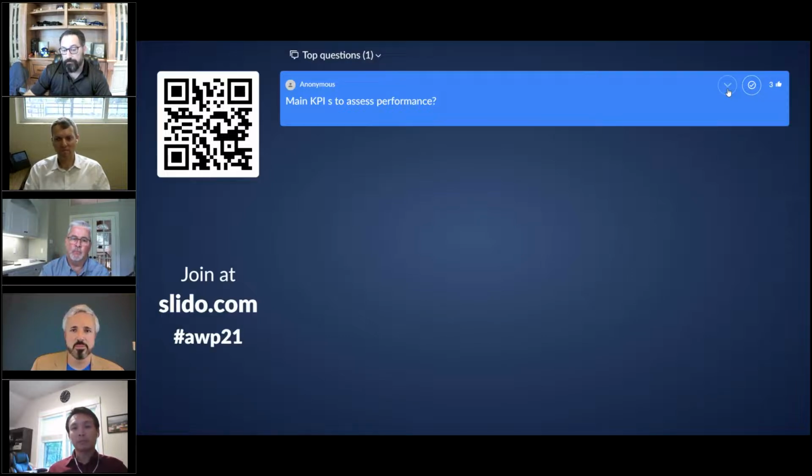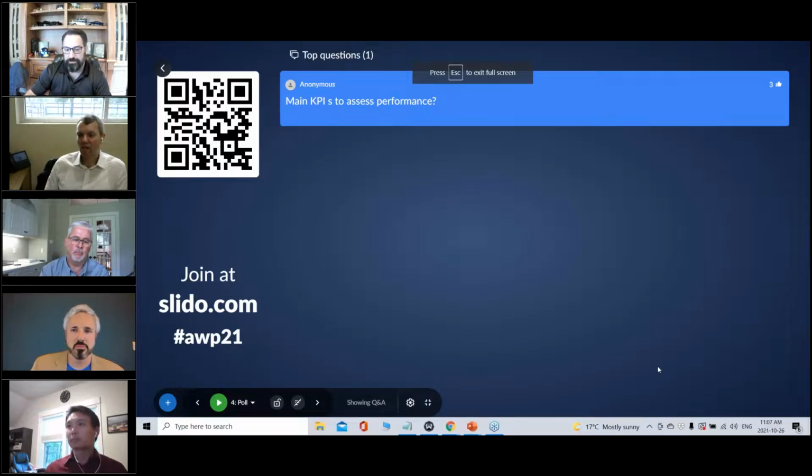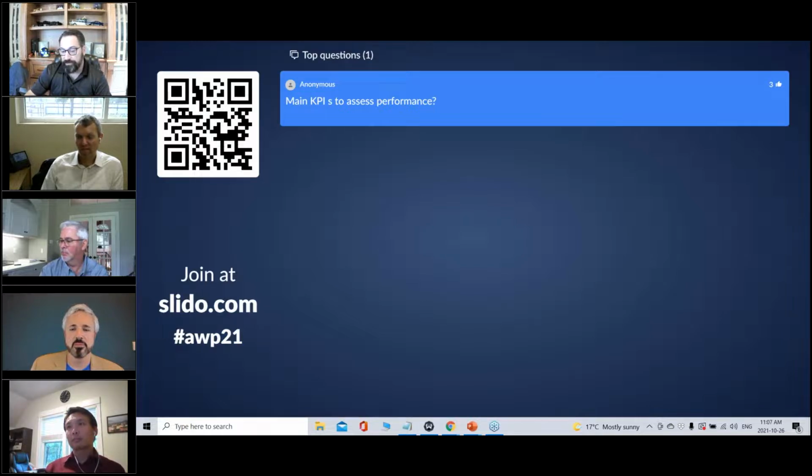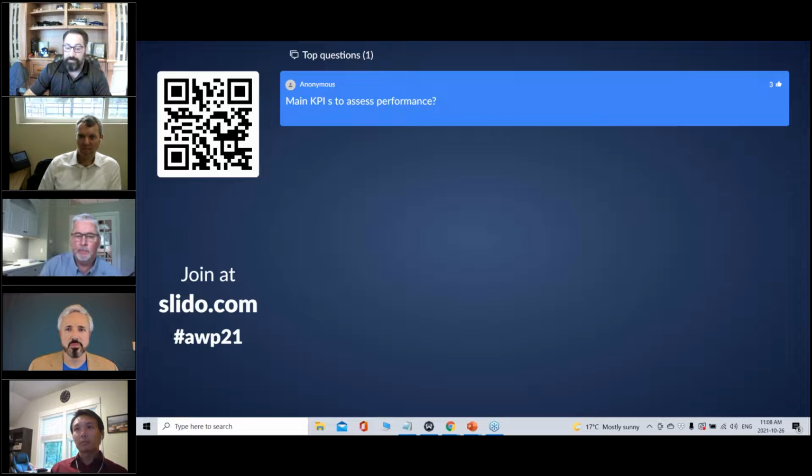Yeah. Early on and during the implementation of a program, sometimes the simplest KPIs are the most impactful. The first one that I would look at is planned versus unplanned scaffold builds. Planned versus unplanned is going to tell you if your program's being effective. If you've got a lot of unplanned, it's time to reassess and fix it before it gets to be too big a bear. That's going to be my main go-to initially, to identify the health. Yeah, and if you follow a more agile approach, you can call that distraction scaffolds, right?